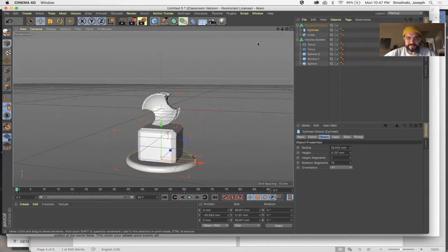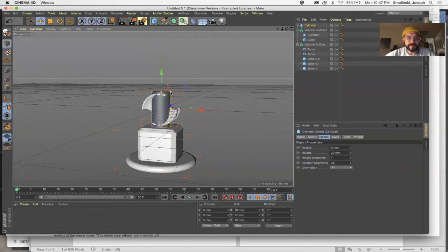And the last thing I'm going to do is just add a little connector. So I'll print this base separate, I'll print the sculptural piece separate, and then I'll make a connector that I'll print separate as well. So 3 pieces that I'll connect together to build this form. So to do that, I'm just going to grab a cylinder. I am going to reduce this down in its diameter, also in its height, okay?